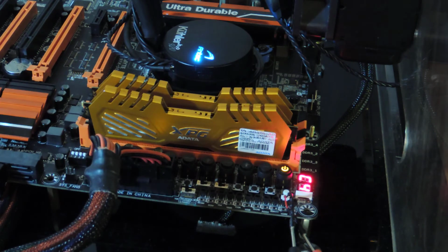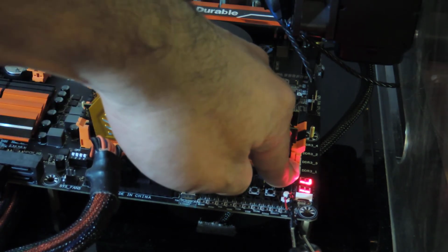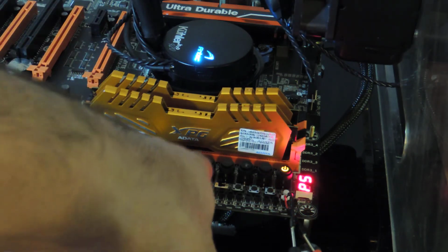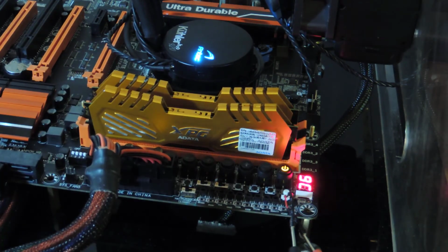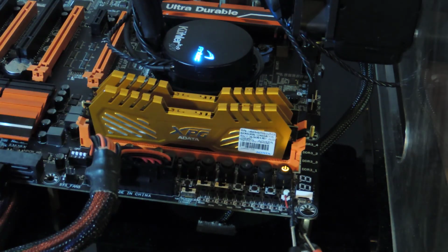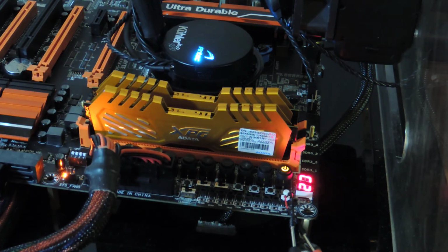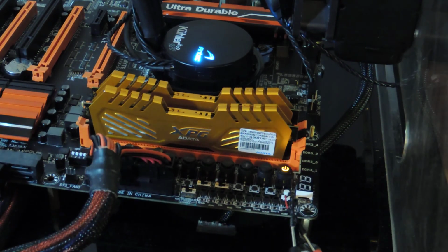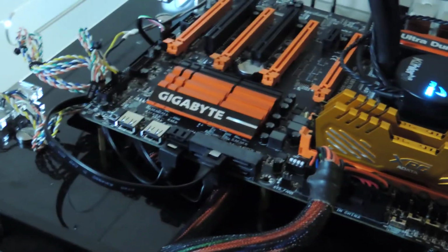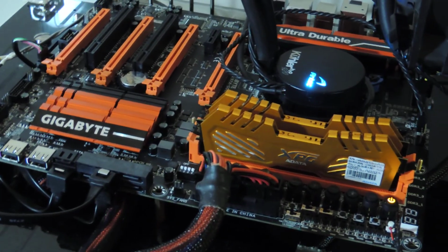If I power down, let's power down. Okay? Well, it doesn't want me to power down. Okay, go into the BIOS, tell me. Okay, system power down. Now if I hit clear CMOS, it's just going to start me back up with the fresh CMOS. But remember, CBAT's going to drain. CBAT drained. Okay? So be careful with that. CBAT's a very powerful tool right here. And great engineering by Gigabyte on their part.